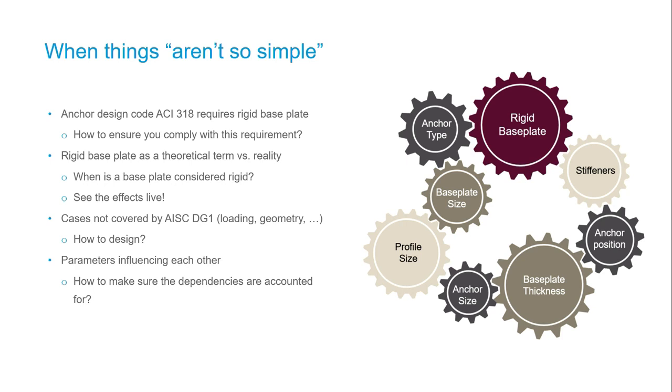If I pull here, you might see that at the edges or at the corner, you get these prying forces. As there is deformation here, and the anchor is not deforming or only deforming a little bit, the corner will basically be pressed against the concrete, and this will have additional compression stresses. As equilibrium still needs to be there, this means that your anchor forces will be increased. And we have seen cases from customers where the customer did some kind of early finite element model, for example using Robot with shell elements and all the stuff. And there was, in most of the cases, a huge deviation. Why? Because of these prying forces. And there were cases where it was not just 10, 20%, it was really significant, sometimes even doubling the load in worst cases.